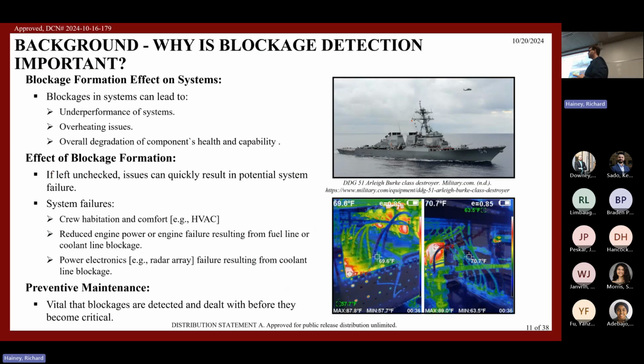About a little over a year ago, we had a bit of trouble with blockages forming within our converter, our converter 2, in this case C2, on one of the cabinets. For some reason that we later determined, we encountered a blockage in the C2 converter. You can see the loss of coolant in the bottom figure here, where the blocked line is featured in blue, while the other non-blocked lines are neon green. So what happened was the coolant to the converter ceased and it tripped.